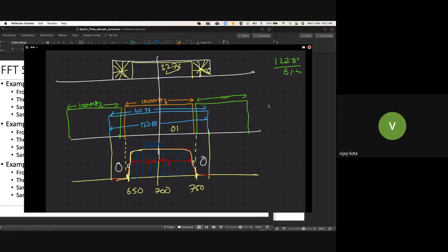Yes, sir. So in effect, 122 megahertz is only for when we do FFT and IFFT on the receiver side. We process that bandwidth and also discard the extra, because we cannot use other than a 2048 or 4096 FFT or IFFT.